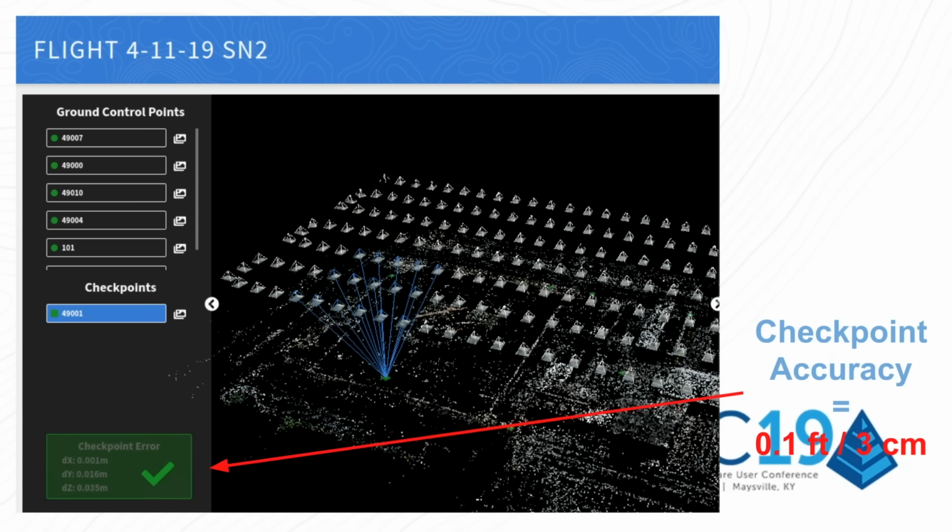It's going to say, hey, I know that the photo centers or the photo positions coming off this particular drone are very accurate, and then it's going to use that in the photogrammetry solution. And we're getting great results. I'll go into that later on, but this is in meters, of course. We're getting around a tenth, sometimes even less, on the vertical and horizontal accuracy with RTK data sets.